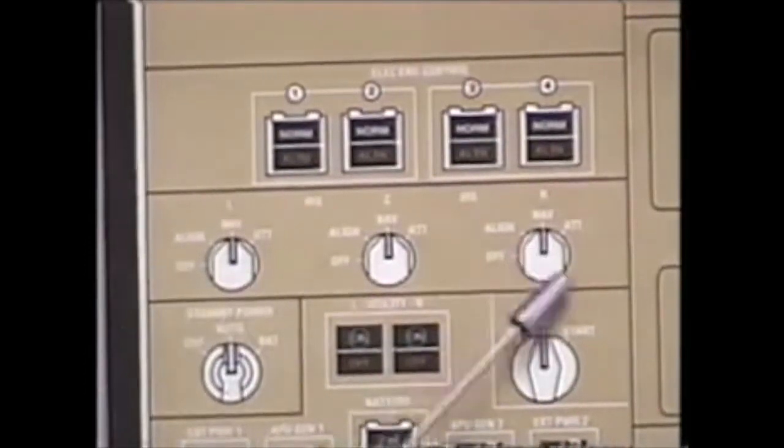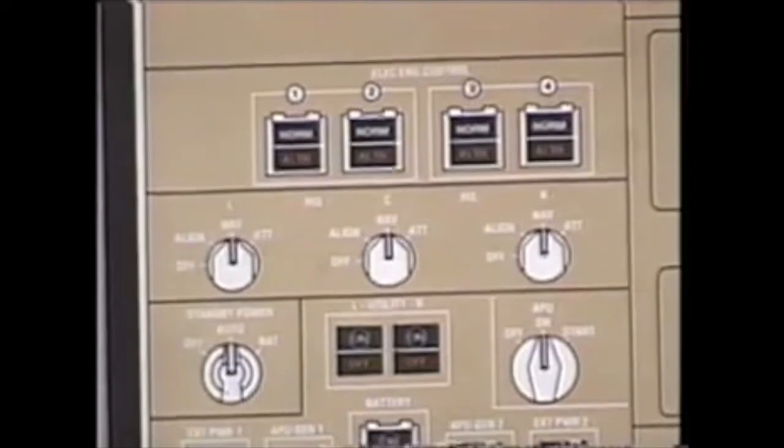If the left or the right IRS was to lose its respective AC bus, it independently can also go to the APU hot battery bus and will run for at least 30 minutes, depending on the availability of your service bus. If your service bus is available, the battery chargers will actually run these two IRSs indefinitely. If the service bus is not available, the APU hot battery bus is actually draining the battery, thus the 30 minutes. During an external walk around, you can tell if an IRS is switched over to the APU hot battery bus by the continuous horn from the nose wheel well.